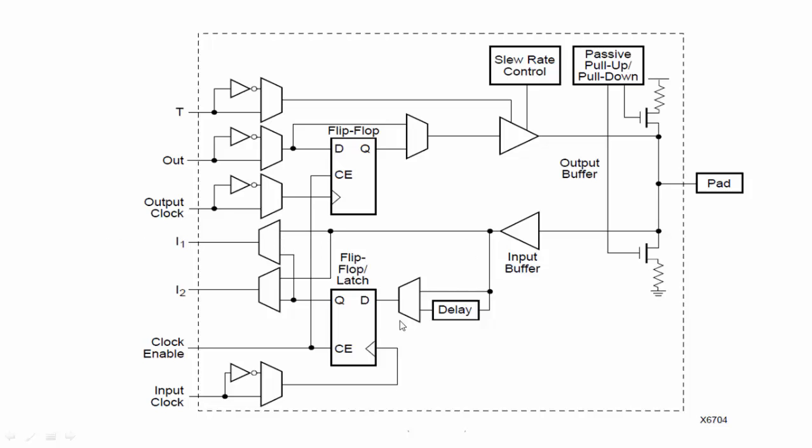But as I said, FPGA works at very high speed, right? So it is always necessary that the external circuitry is synchronized with it, and in order to synchronize you have to pay attention to the instances when the input will come inside the FPGA and the instances at which the output will go outside the FPGA. For that purpose you always need to add delays.